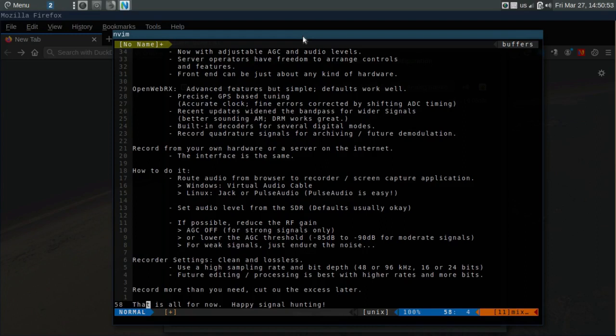The input to the analog to digital converter is generally fixed, and it's high enough to get signals above the noise, and it's not so high that it's going to overload the ADC. What you're really doing with RF gain on an SDR is adjusting variables in the code that adjust the gain setting in the virtual realm.